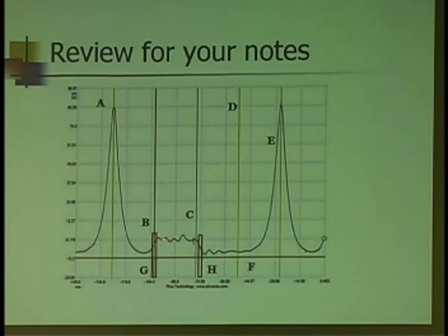Okay, now we have the exhaust stroke, heading back towards TDC at C. Because the intake opens while the exhaust valve is already open, you're not going to see exactly when that event occurs, but the ramp is still something I can use as a reference. The middle of that ramp should occur about 20 degrees after TDC. Again, if the intake cam is off for whatever reason, it's going to be a noticeable change, left or right.